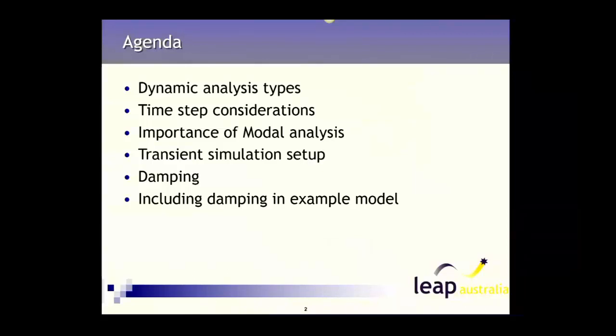Okay, so I'll talk about the different dynamic analysis types, time step considerations, and also how modal analysis fits into the whole picture. So I'll show you a transient simulation setup, or at least a model that's being solved, and also talk about damping, and also show you damping in a model and how it affects your results.